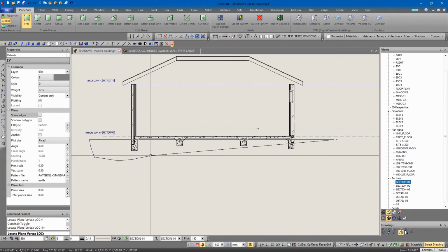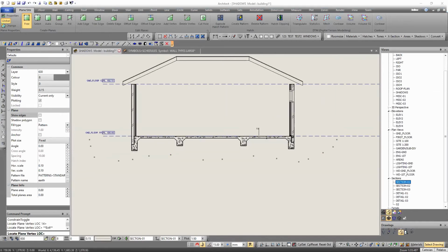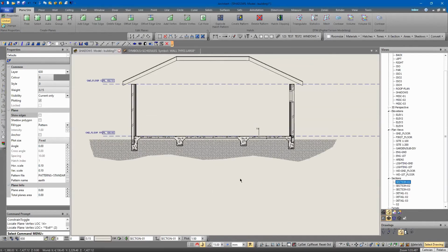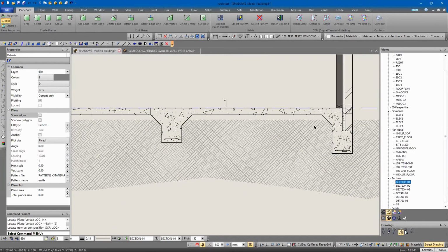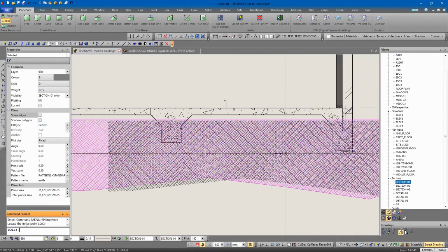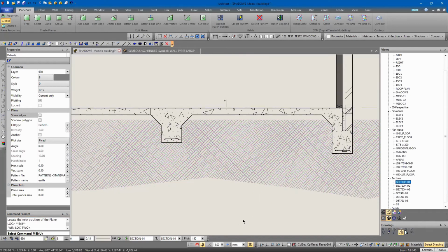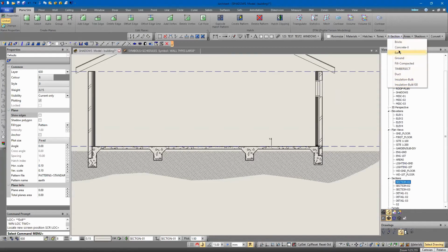And so instead of actually trimming, putting my plane in around and following every stump or every internal beam, edge beam, all I've done is I've just put that in, and I would move that Z -10, and that my earth will be behind everything else. If I wanted to put some sand in, I just changed the settings for sand.